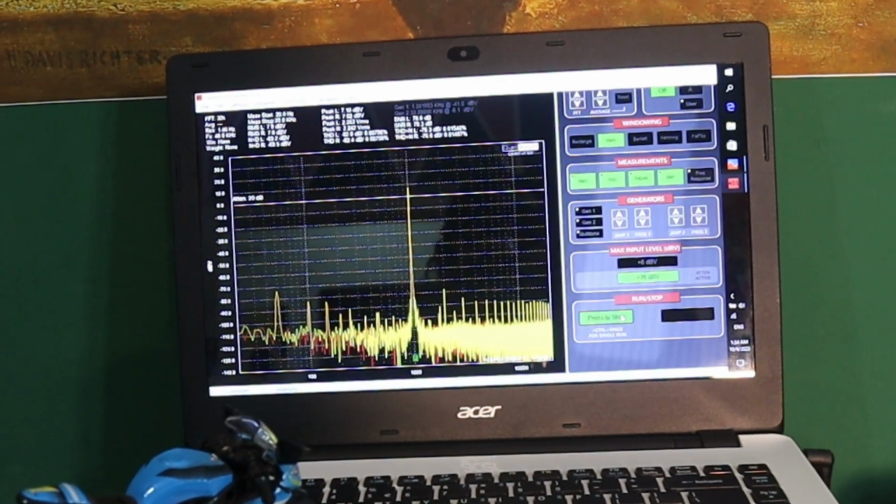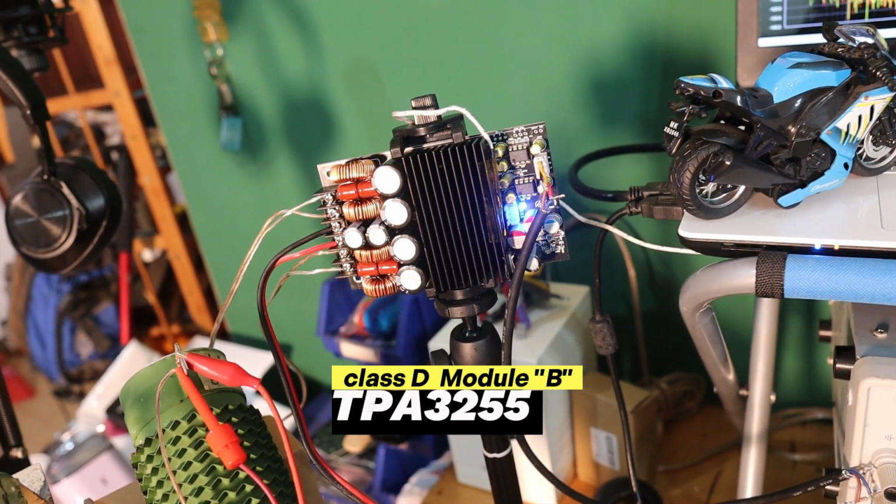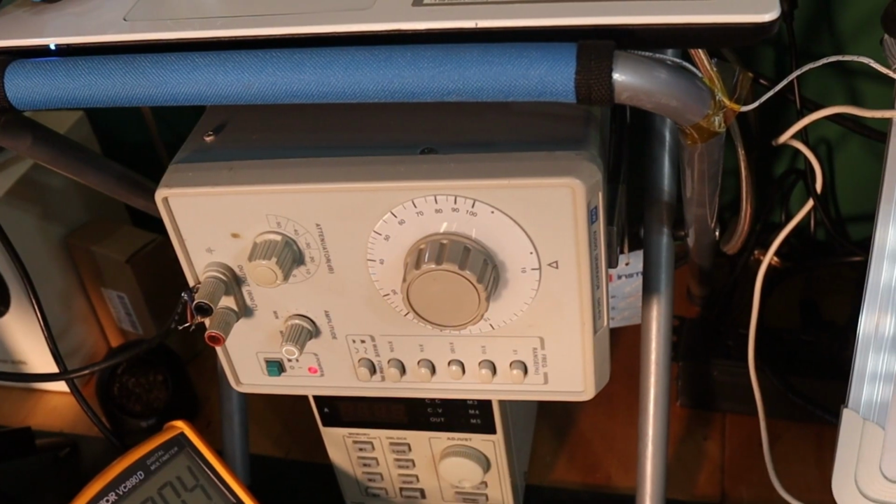Quant Asylum. I'm having a little problem on the bridge style load configuration as I'm testing the TI chipset, the Class D power amplifier with an analog input, particularly the TPA3255. A little bit messy because of the bridge style load configuration with respect to the grounding of the PC and also how to isolate that with the traditional equipment that I have.